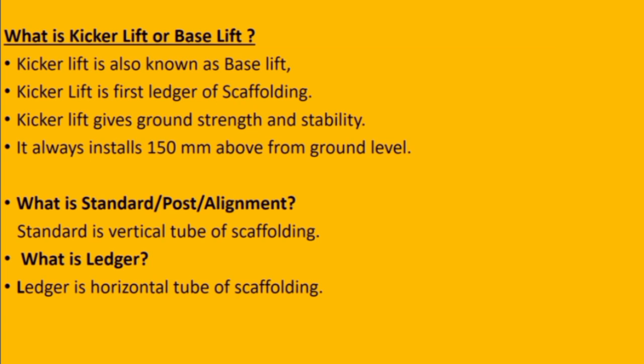What is kicker lift? Kicker lift is also known as base lift. Kicker lift is the first layer of scaffolding. Kicker lift gives ground strength and stability. It is always installed 150 mm above ground level.